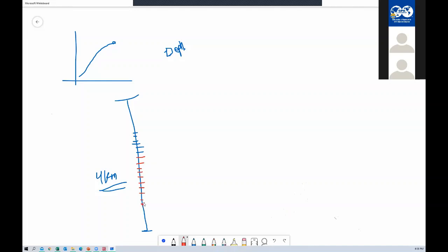At each of the depths, you are going to understand with the given stresses whether your rock is going to fail or not, and how much strain you are going to develop. You will try to do all those analyses, and you will be doing it from top to bottom, wherever data is available to you.